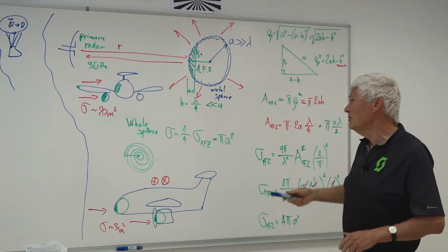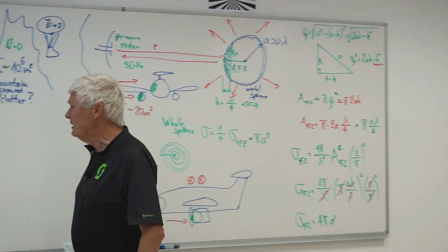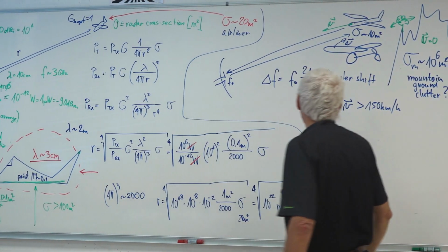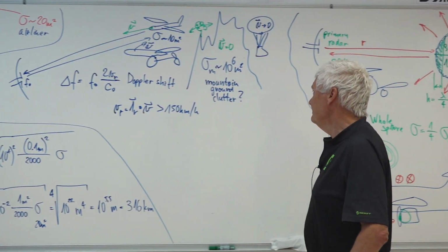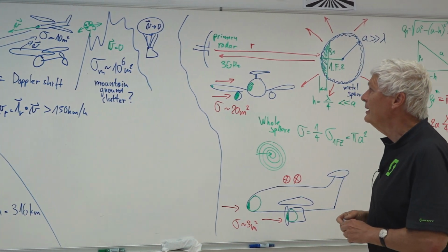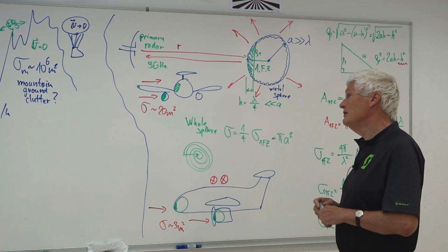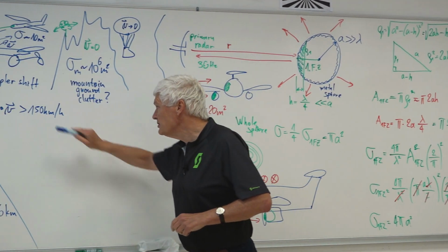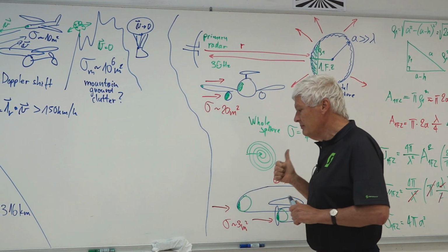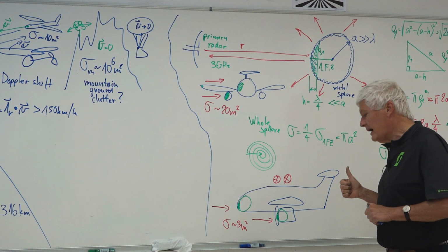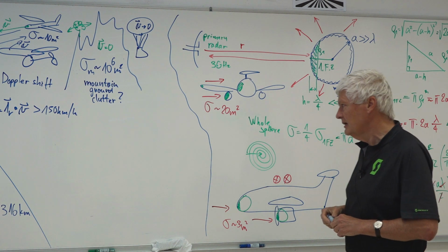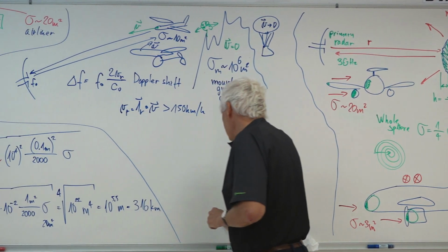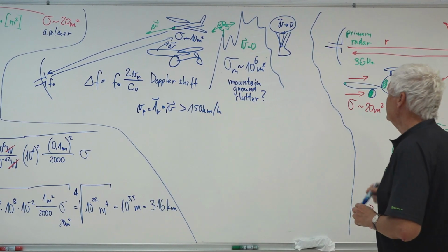The primary radar, I'll say it's okay for the military. The military always think about a non-cooperating target like this one here. But for civilian use, you have to use a pulse Doppler radar, so transmitting pulses and measuring the Doppler shift, and you only detect targets that do have enough Doppler shift on their frequency. It's not that easy to do this. This makes the primary radar quite unreliable.